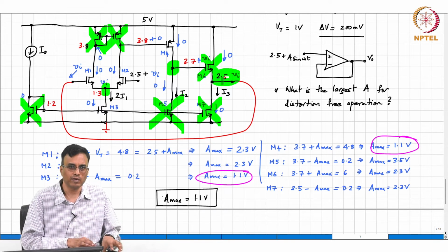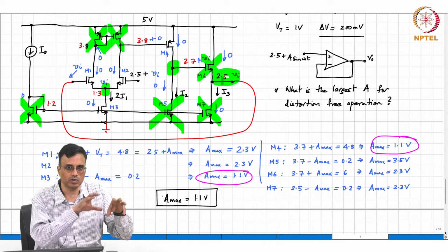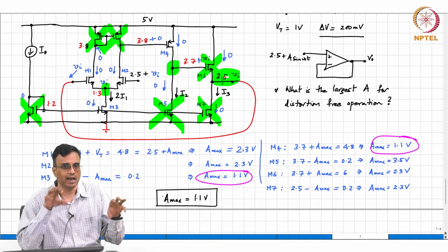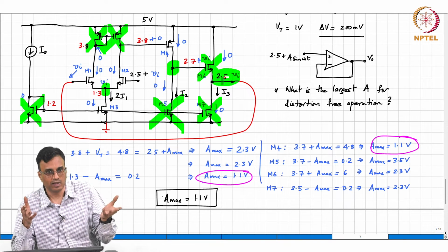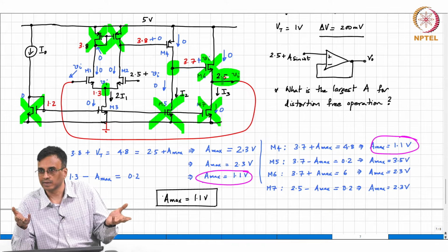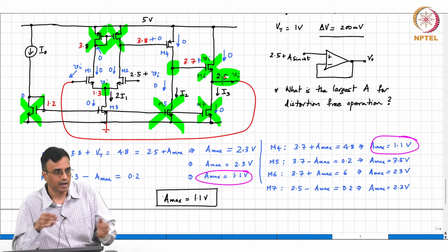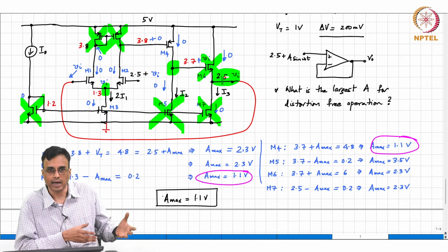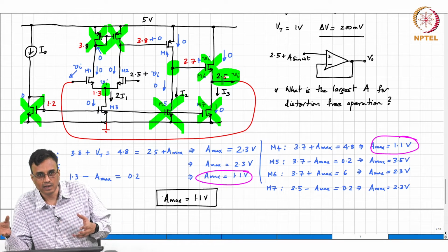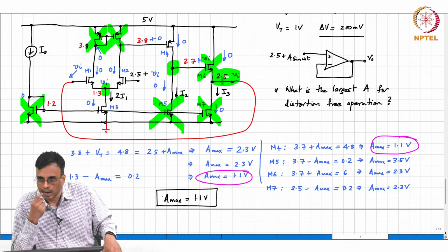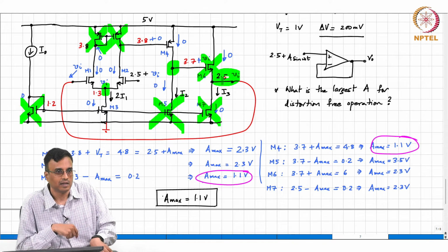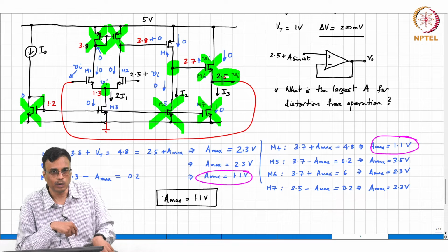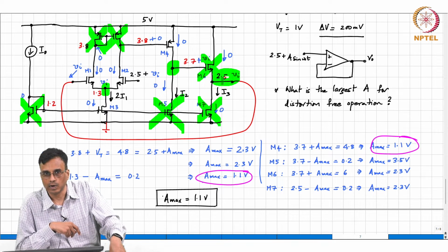Now, to get gain, what are we doing? Each amplifier stage has got some delay. When you cascade amplifiers, you get more delay. Why did you cascade amplifiers in the first place? To get gain, correct. But along with gain comes delay, right. If you want more gain, you get more delay. And now, if you have a negative feedback loop with a lot of delay in the loop, what will potentially happen?